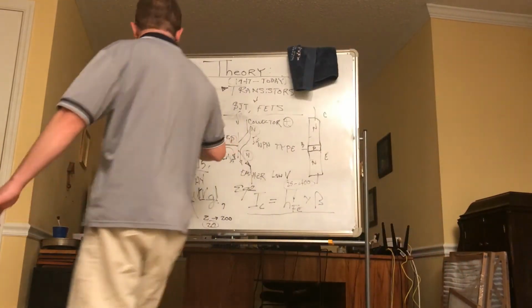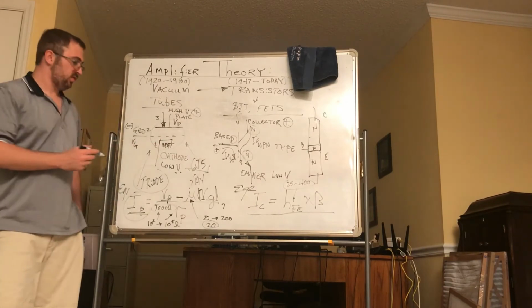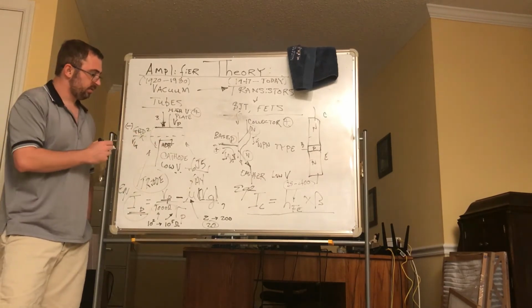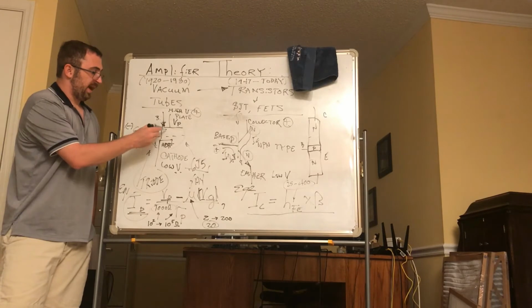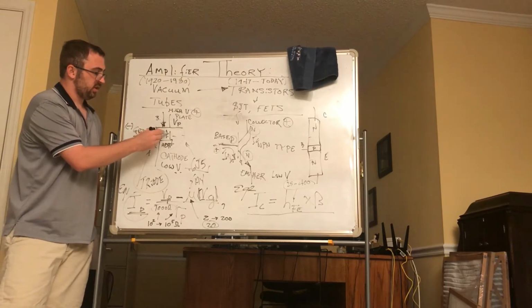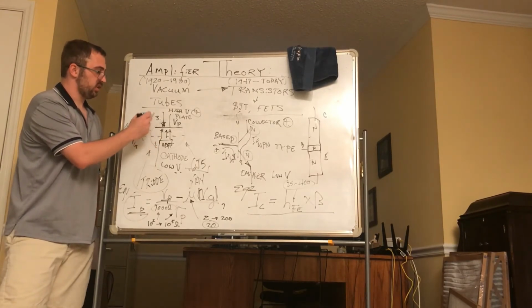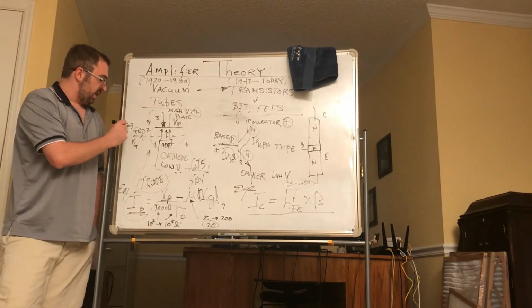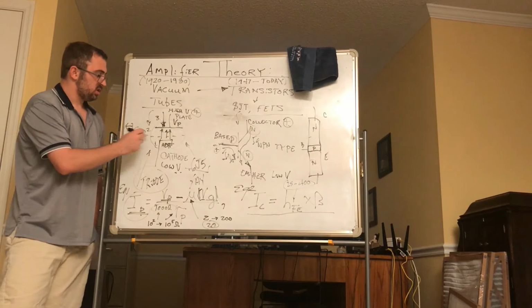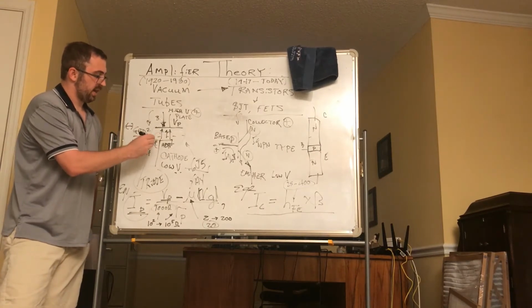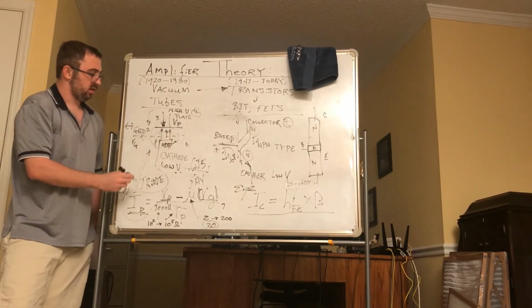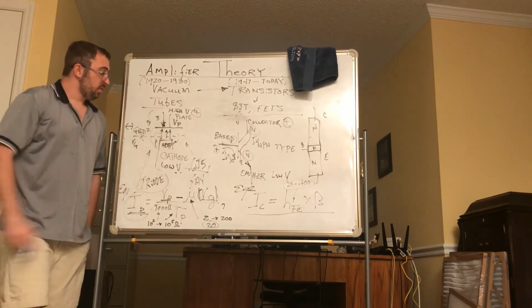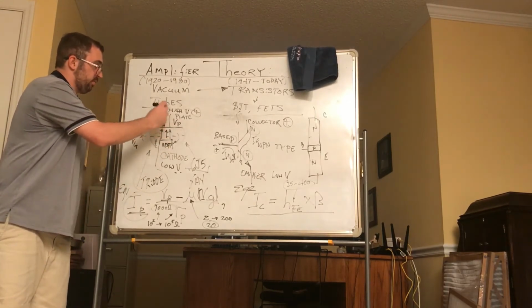In the tube's case, it's very different. If you cut the grid off, a maximum current would flow, the electrons flowing this way, so the classical conventional current would be shown this way. And it takes a negative potential to stop or repel the electrons back towards the cathode, which is this lead here, and the grid is in the middle, then you have the plate.